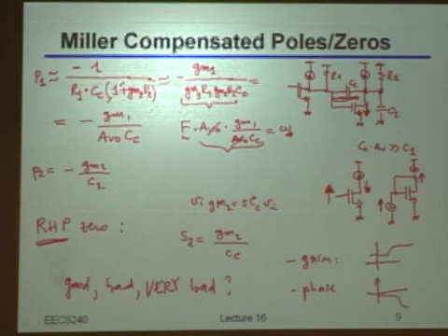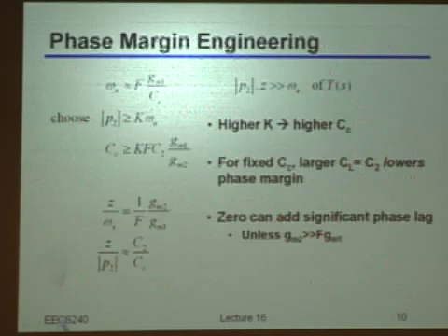So you go minus 90 degrees phase shift after the zero, while still you don't have the crossover there. And so I guess then we can use the last few minutes to discuss what is really needed here at this point, now that we have all the complete configuration. What we are going to do is really some phase margin engineering, right?